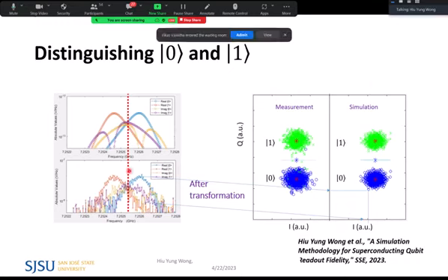We actually measure at a center frequency. Because all these microwave pulses have real and imaginary parts, because they have a phase. So if you are at 0, your peak frequency shifts lower, or shifts higher due to 1, and you have a different real and imaginary part combination. When you read it at this frequency, you will have a different so-called IQ blob. Here it shows the in-phase and out-of-phase quadrature, but it's just the same as real and imaginary.